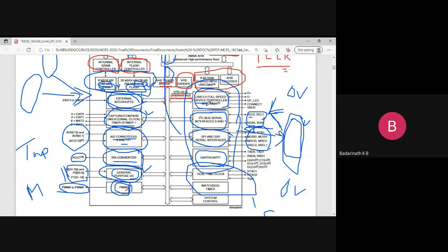So whenever you want to build a project where your project should provide pen drive support so that you can read the file system, no, you cannot go for LPC2148. This is where you should be able to think about what the limitations are.